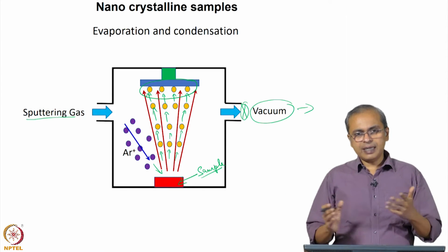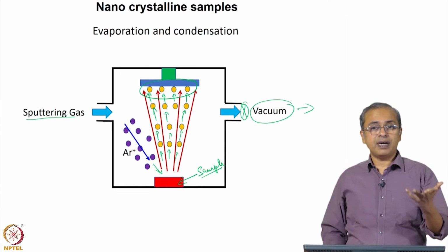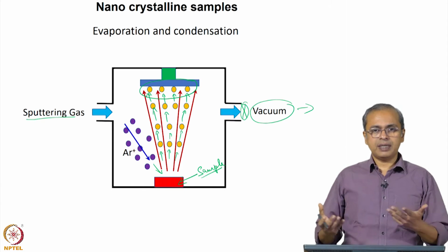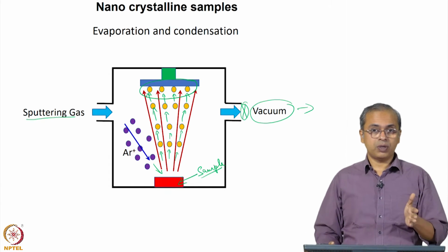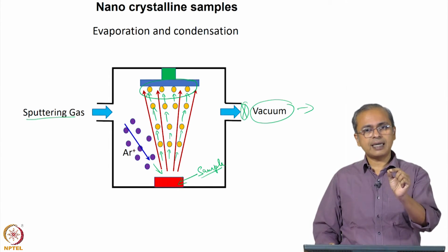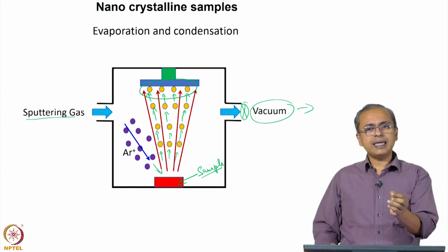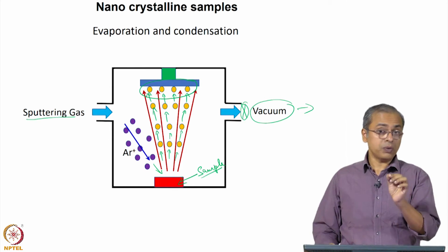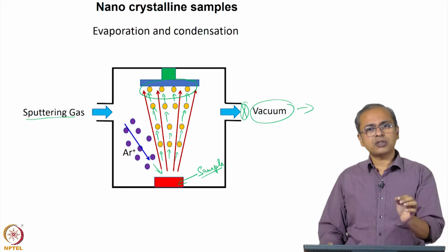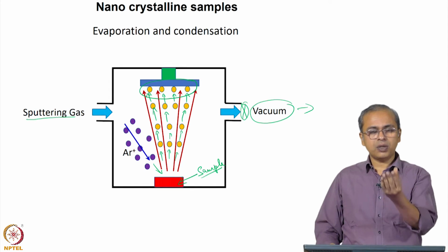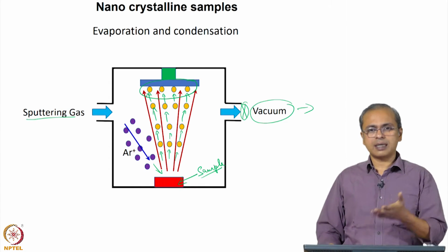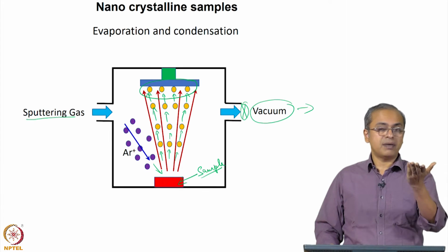In these three, relatively speaking, the thermal evaporation process is very fast. Normally your vacuum chamber may take half an hour or 45 minutes or even an hour to reach the low vacuum that you are interested in. Once you reach that low vacuum, in the thermal evaporation process, if you start raising the current, you have to do it gradually so that you do not have non-uniform heating. If you do it gradually, in about 30 seconds to a minute, you will have that boat getting close to white hot, past the red hot condition, and the material will evaporate.